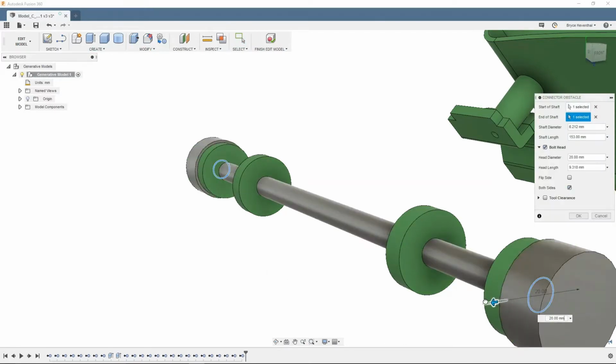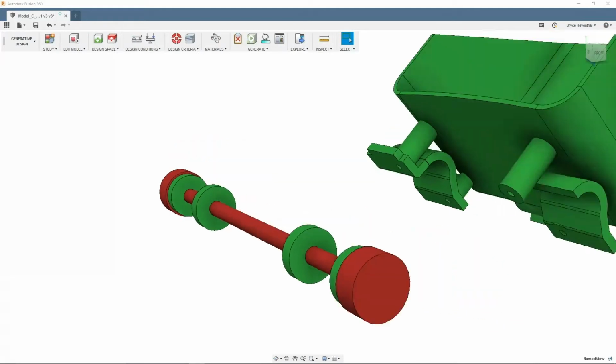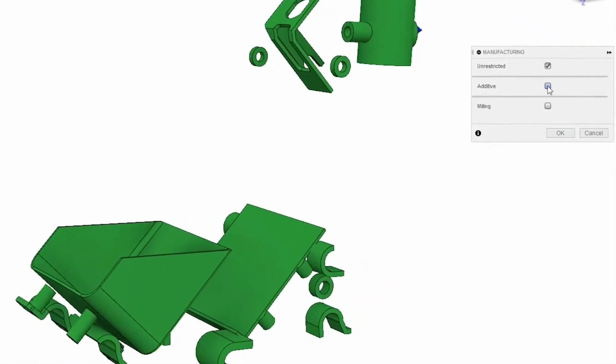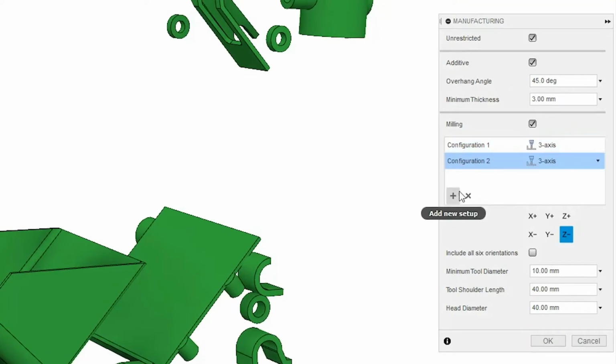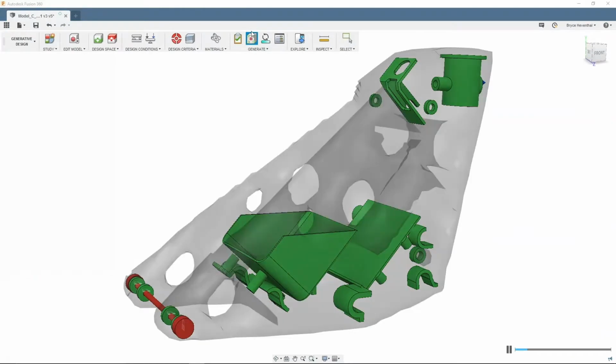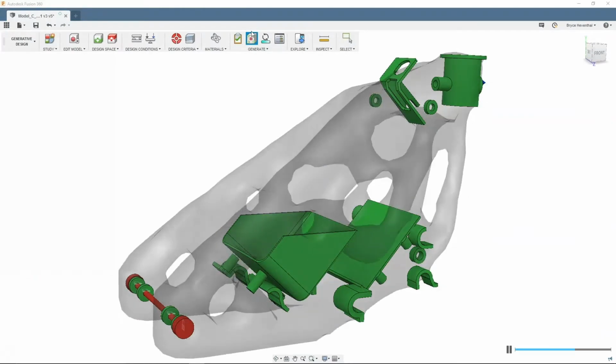From there, the remaining geometry will be designated as either preserve or obstacle regions. Then, load cases representing the real-world loading conditions and materials are defined, and used to weigh the results against an objective to lightweight or create the stiffest part possible. From there, the manufacturing constraints are defined. Will you use a 5-axis, a 3-axis, or additive manufacturing process, or other? These definitions will account for how you take that digital model into a tangible asset.